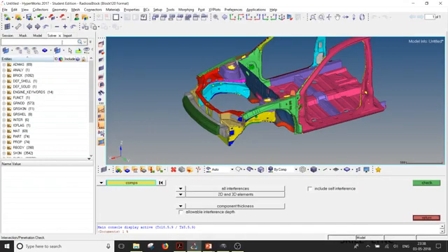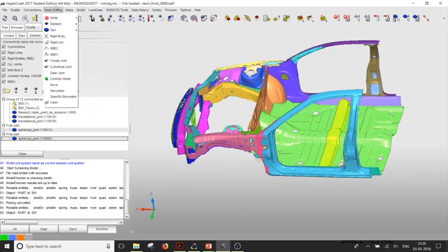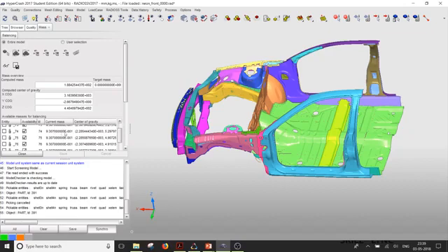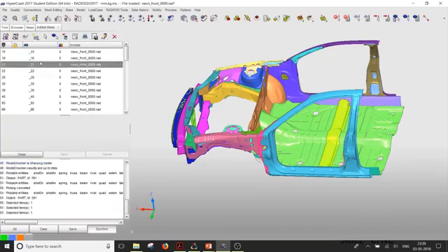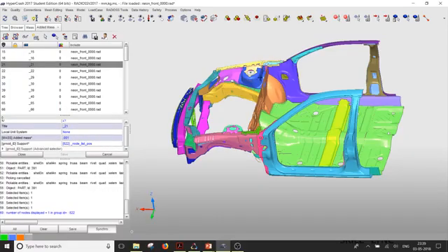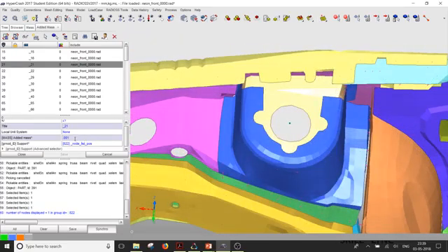In HyperMesh, in the Solver browser, you can see all the added masses listed over here. Now you can choose to delete these. You can always list them down over here in model balancing, and you'll see the whole list along with the exact numbers. Apart from that, you can always go from the browser, added mass. You can double click on this and you'll see what was the added mass on that particular node. So at this particular node, the added mass has been 1 gram.